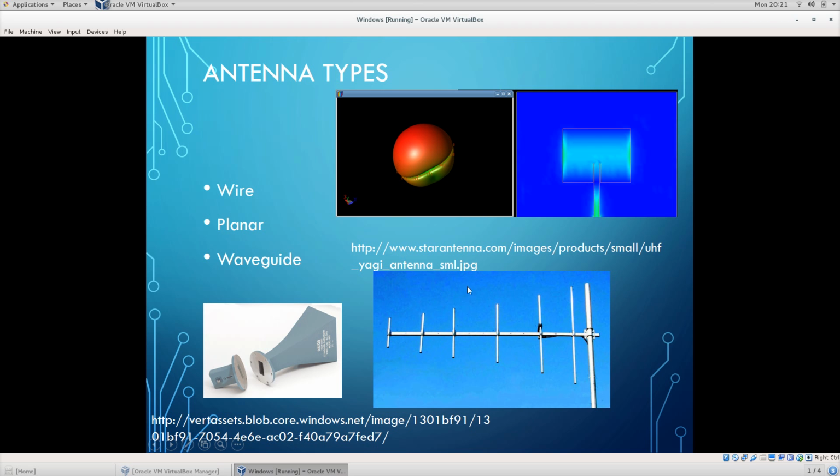This is what's called a Yagi antenna. It's a highly directional antenna, and the idea is that right here is where you have your drive. So your RF drive, you can actually see the feed point here. There's a reflector element here and several directors going forward. Now you can actually make these things longer and longer, and if you do the taper correctly and set some stuff up, you can get extremely high gains with these types of antennas.